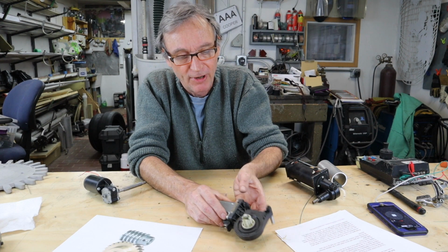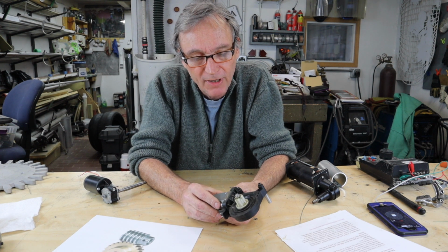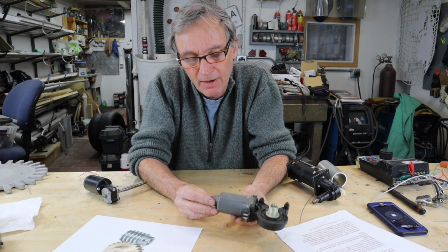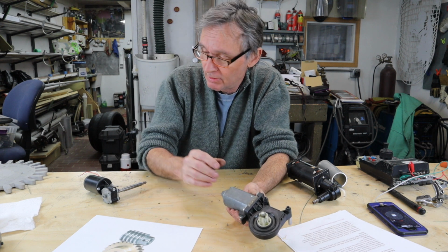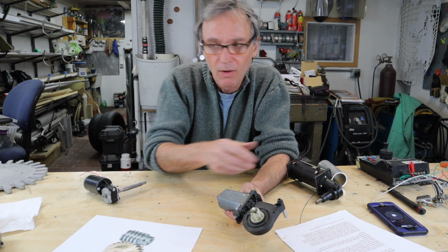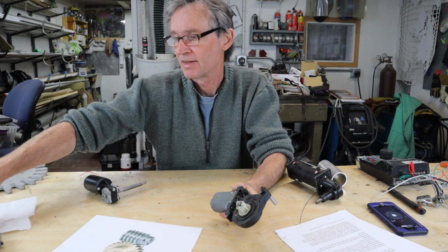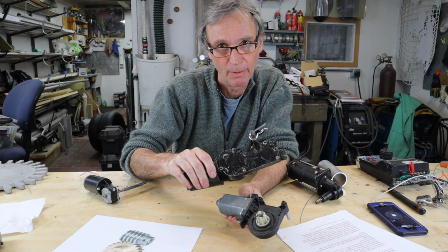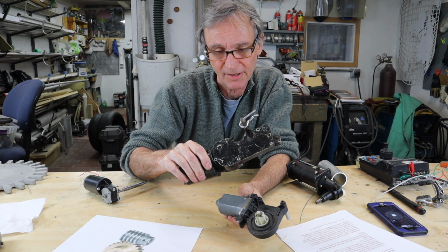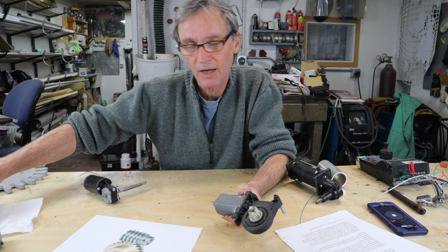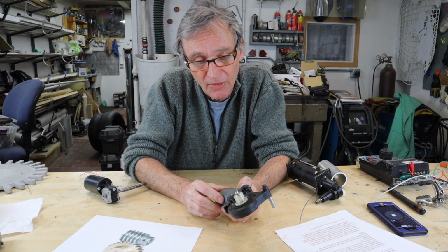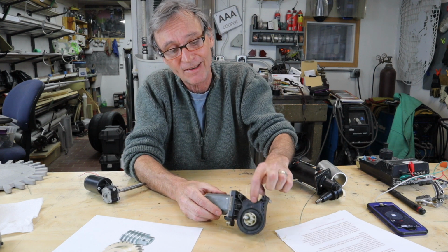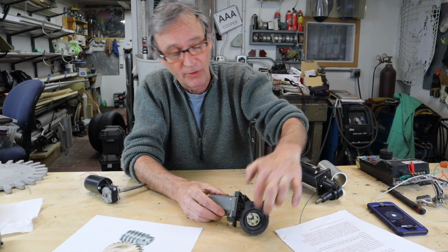And we're back just briefly again on worm drives. It's worth noting this is an electric window operator. This is a windscreen wiper motor, but we're going to look inside the guts of this a little bit later. But anytime you need very high torque and you don't mind low speed, that's where you'll see this classic arrangement of the worm at the top and the cog underneath.